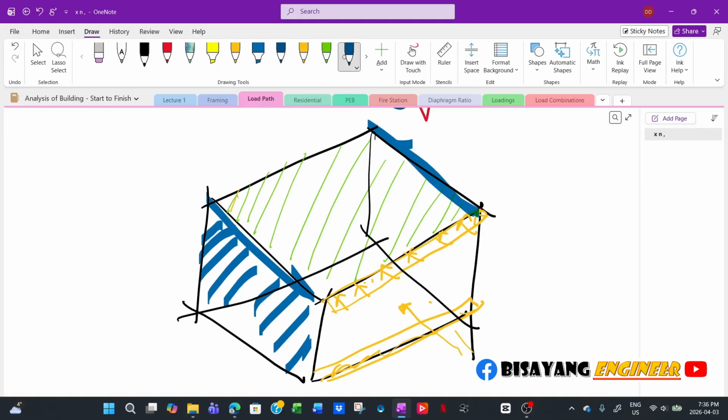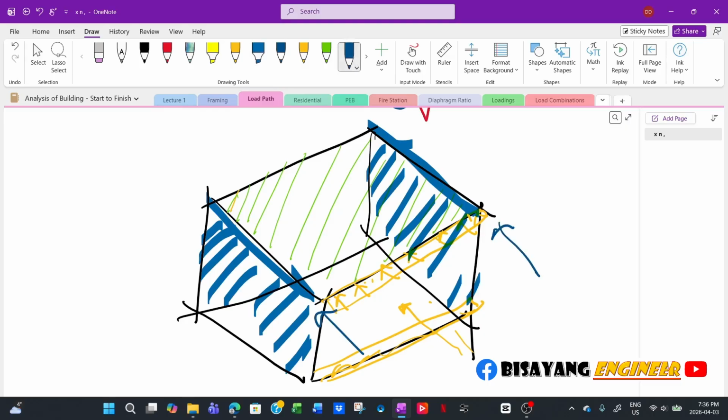So this wall is subjected to a horizontal load. But what's resisting that from sliding? Because the load now is horizontal, the total load there will now be resisted by this beam or this wall here. So it is resisted by that wall, and then this one will be pushing against the soil on the other side, on the back side, as that's passive resistance.